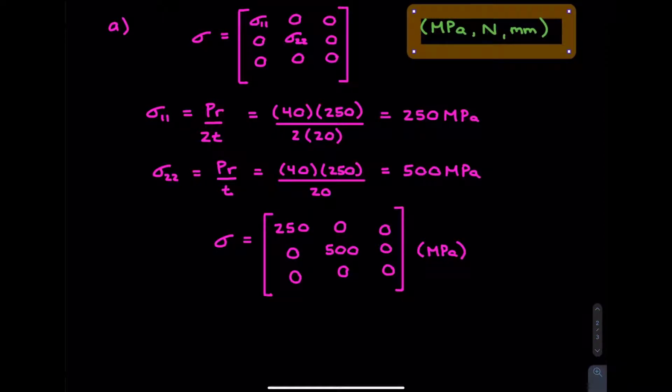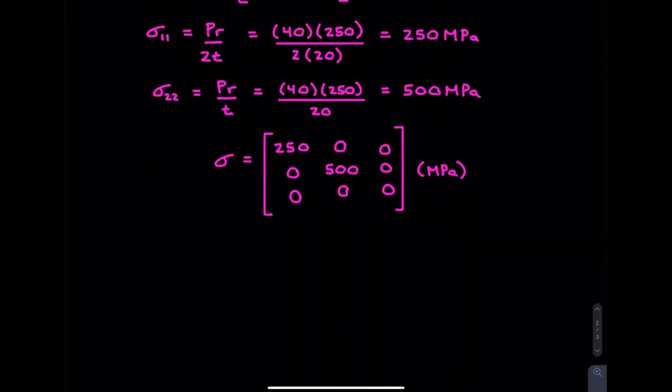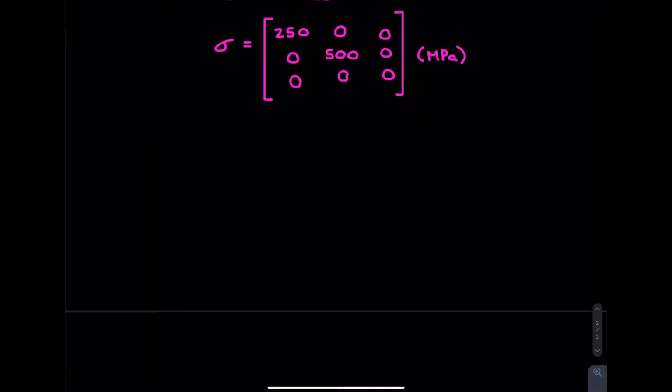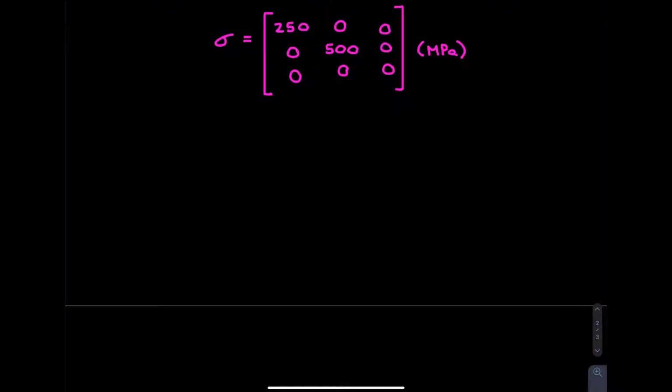So what I'm going to do is scroll down right here, and we're going to start talking about, okay, well, I have the stress tensor. How can I find the strain tensor? So the key to this one is if we look up at our stress tensor, we see that sigma 1,3 is equal to sigma 2,3, which is equal to sigma 3,3, which of course is all equal to 0. Why is this so nice? Well, this means that we have our plane stress. And if we have our plane stress, well, that means that we don't need to go to that 6x6 very gross looking thing.